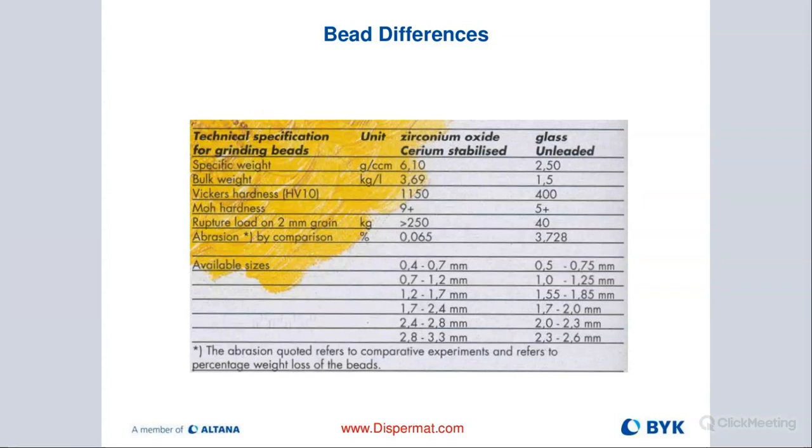Usually the very low cost beads, even though sometimes you get them in ceramic, if you look at them closely under the microscope, might not all be perfectly spherical. So you really want to look at where you're getting your beads from, and the quality there is really important. Always go with the heaviest bead you can find that's not contaminating your slurry.